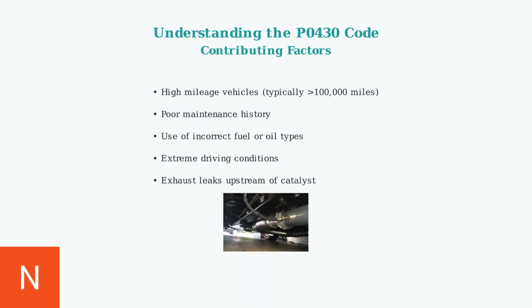Several factors can contribute to catalytic converter problems and P0430 codes. High-mileage vehicles over 100,000 miles are particularly susceptible, as are vehicles with poor maintenance histories. Using incorrect fuel or oil types can contaminate the catalyst, while extreme driving conditions accelerate wear. Exhaust leaks upstream of the catalyst can also affect readings and trigger false codes.